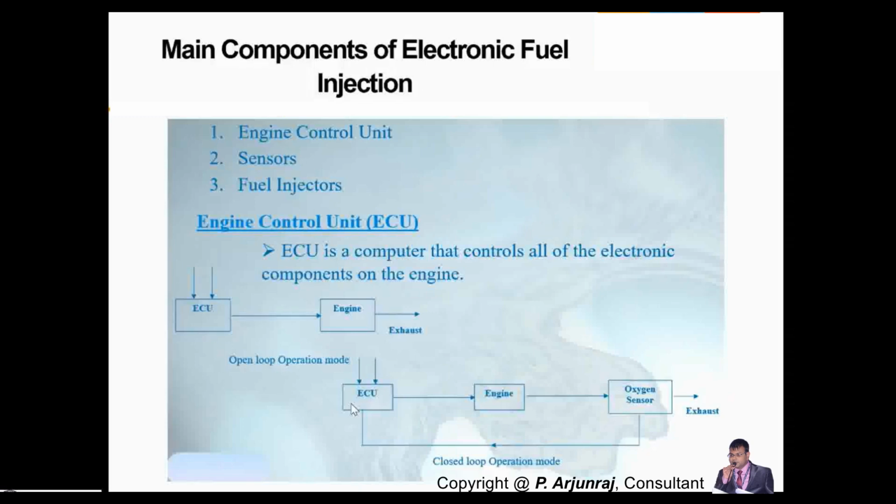This is very important, because whether the injection or ignition is earlier or later will also affect the valve overlap period, and that will cause corresponding problems with respect to the engine power output and also the torque output of the engine. Power is directly proportional to torque, and power can be defined as 2 pi N T by 60,000.